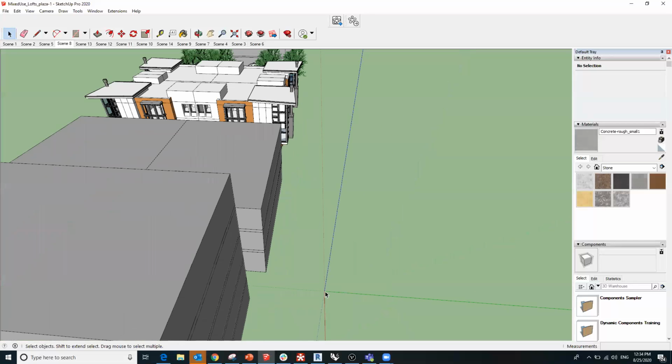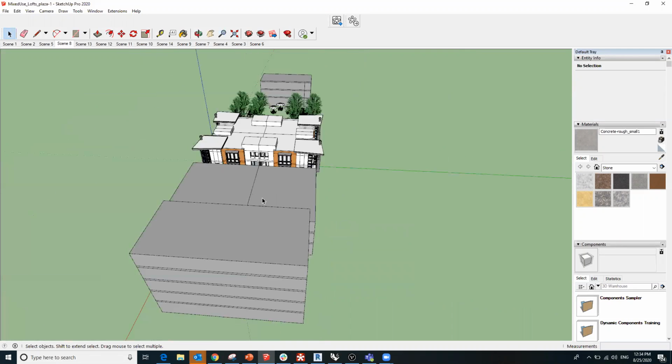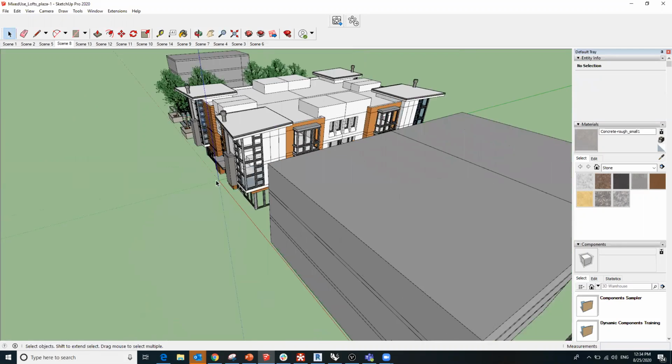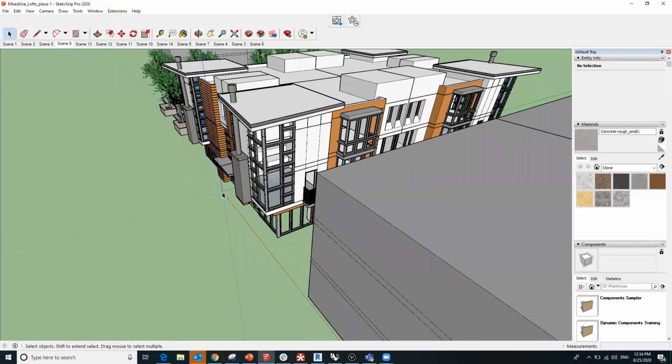And then a way to double check that is if I, again, right click on that, I'll have the option to reset become available, where if I reset that and it's actually in its internal origin place, I no longer have the option to reset that. So if you've moved this point to a certain location and you're exporting to Revizto and can't figure out why it's not picking that point up, just know that it's always going to read that reset, again, internal 000.